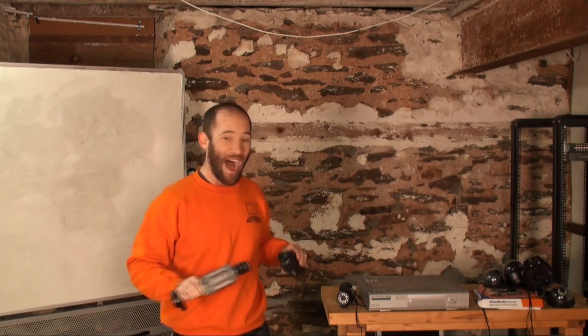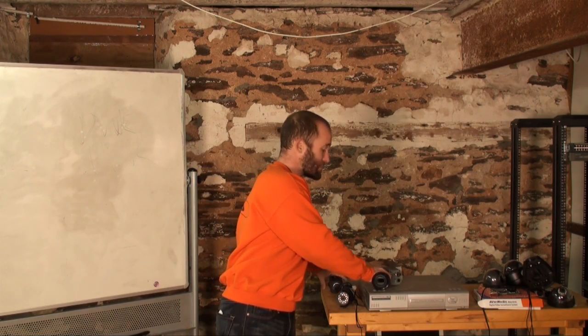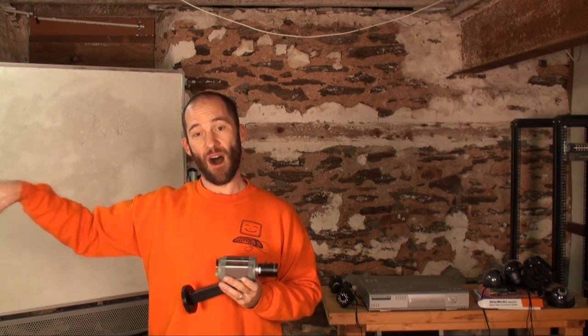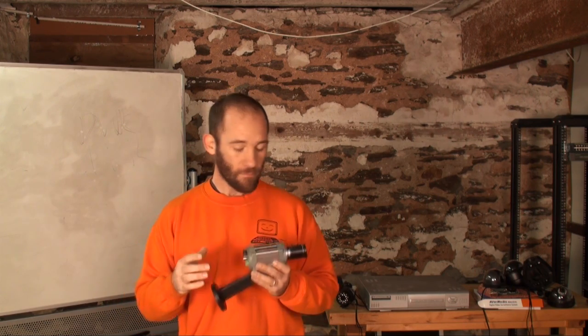Those are called hybrid systems. So those are the basic systems. When you're researching different systems, that's what we're talking about. DVR, dumb cameras using BNC, basically coax cable. NVR, network video recorders, are using IP cameras. Basically what they do is through the TCP/IP, they pull in the video stream that is coming from the IP camera, and then they store it onto that server.